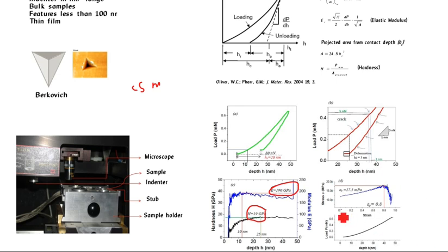And we have found out the stress-strain plot from the load-depth plot, and we found the yield stress to be 17.5 MPa. And another interesting aspect is, if we magnify the load-depth plot, we found that there have been some discontinuities in the load-depth curve.